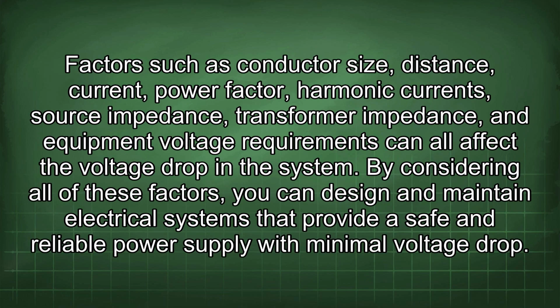Factors such as conductor size, distance, current, power factor, harmonic currents, source impedance, transformer impedance, and equipment voltage requirements can all affect the voltage drop in the system. By considering all of these factors, you can design and maintain electrical systems that provide a safe and reliable power supply with minimal voltage drop.